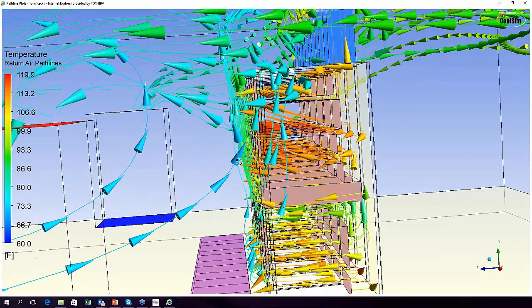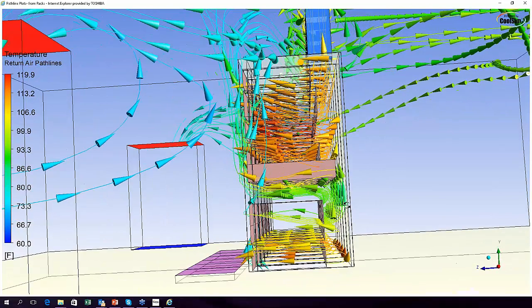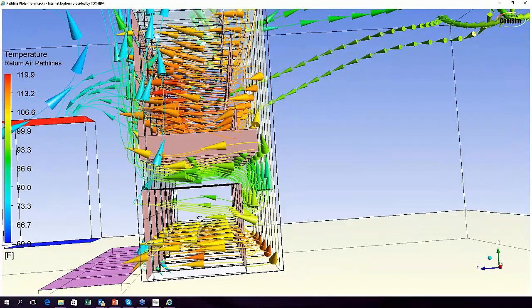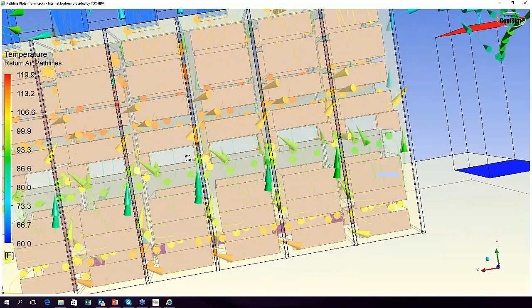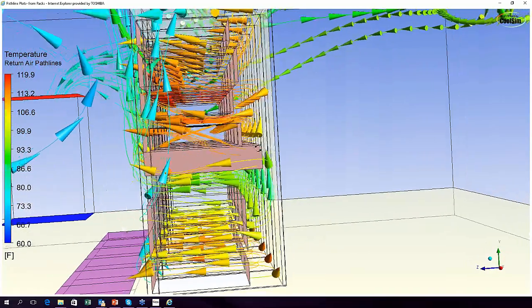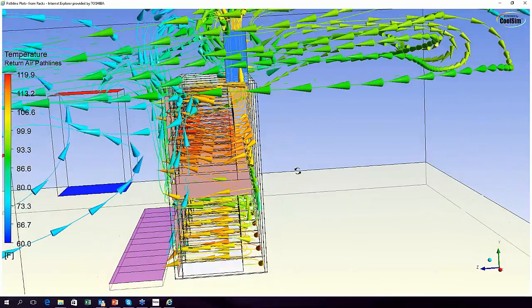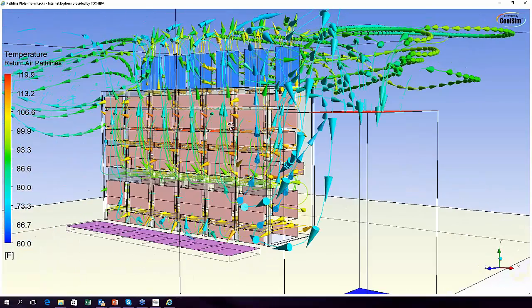So there's what's going on inside that rack, and this is quite realistic. What's happening here is this bottom server is being blocked by the one above it. As air comes out of the bottom server, it bangs into this one. By the way, this one's blowing air pretty hard, I think sideways. So you get a lot of mixed up things going on, a lot of pressure variation, and because there's no active chimney here, it's just dumping out the top, so there's some flow impedance in this direction, and guess where the air therefore goes? To the front.